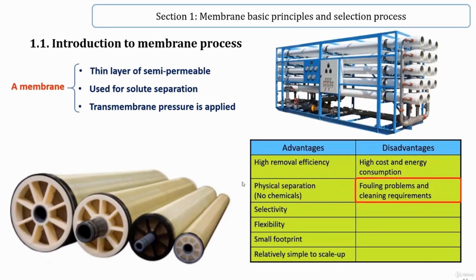Membrane separations also can encounter a significant problem of fouling of the membranes while processing some types of feed streams. This fouling can inhibit the rate of permeation through the membranes and that makes them incompatible for such applications.